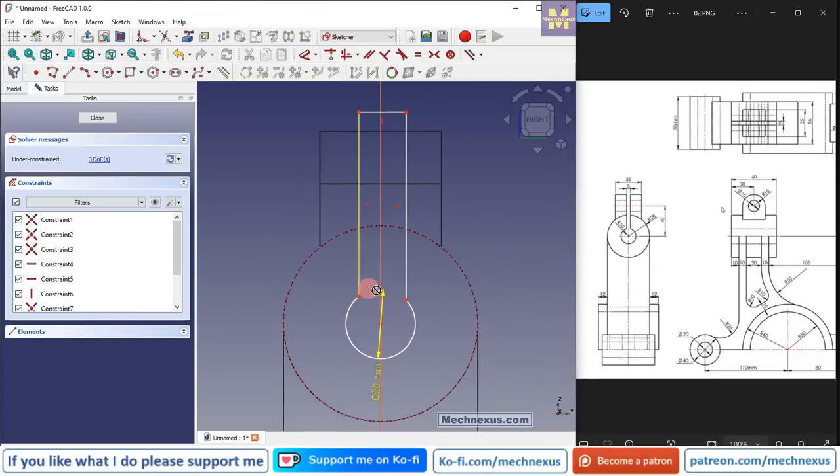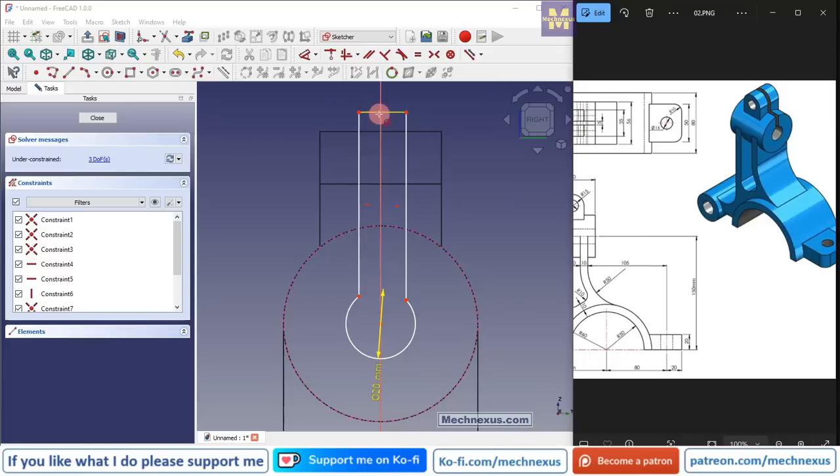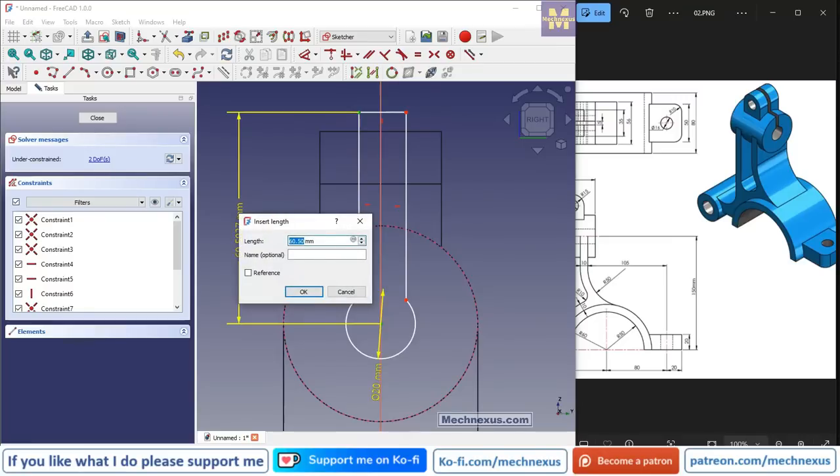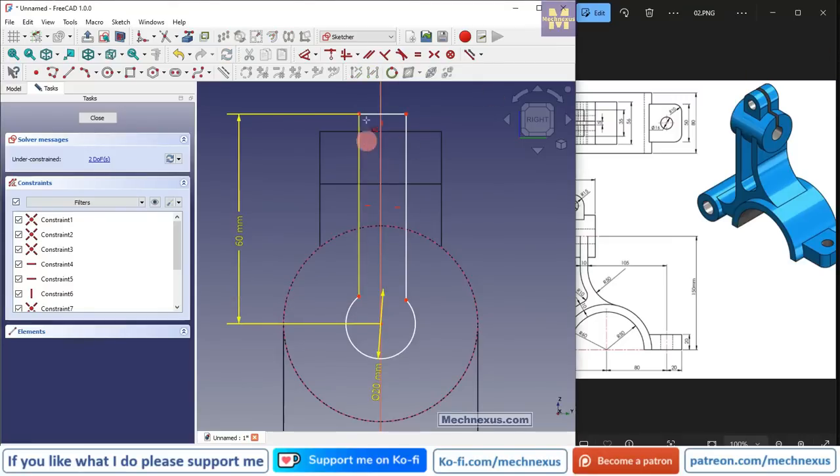and as we wanted to remove the material, this height is not a constraint for us, so let's give 60 mm, so that this should become outside of the body, and I will make this and this symmetric.